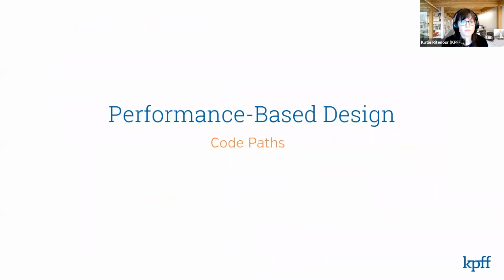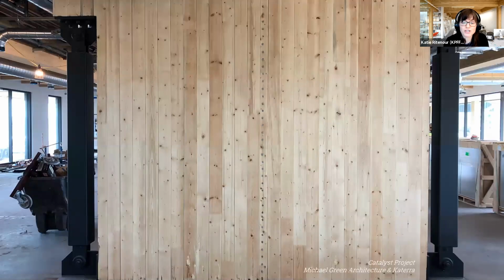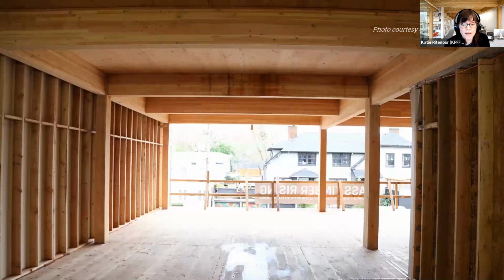So moving on to the performance-based design code options available, we have mass timber rocking shear walls, we have mass timber shear walls with buckling restrained brace hold downs, we have mass timber pier and spandrel systems, and we have, of course, mass timber diaphragms available to us.